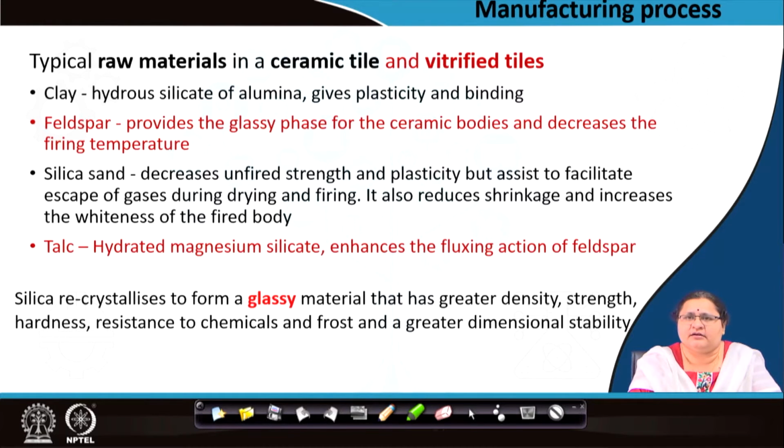This silica recrystallizes to form the glassy material. So you have to heat it at a higher temperature so that the silica recrystallizes and gives the added qualities. It makes it frost resistant, chemical resistant. The dimensions do not change. There is no warpage, minimum warpage, as we had seen the phenomenon in clay.